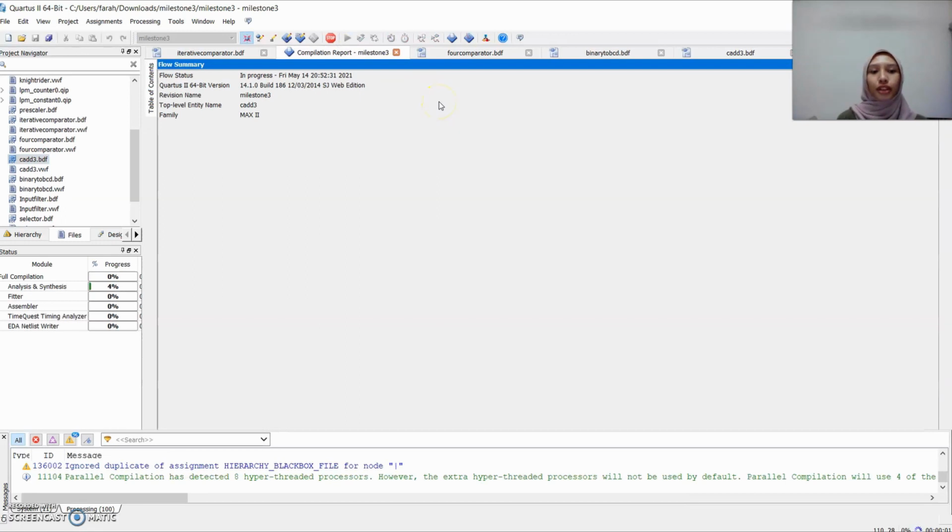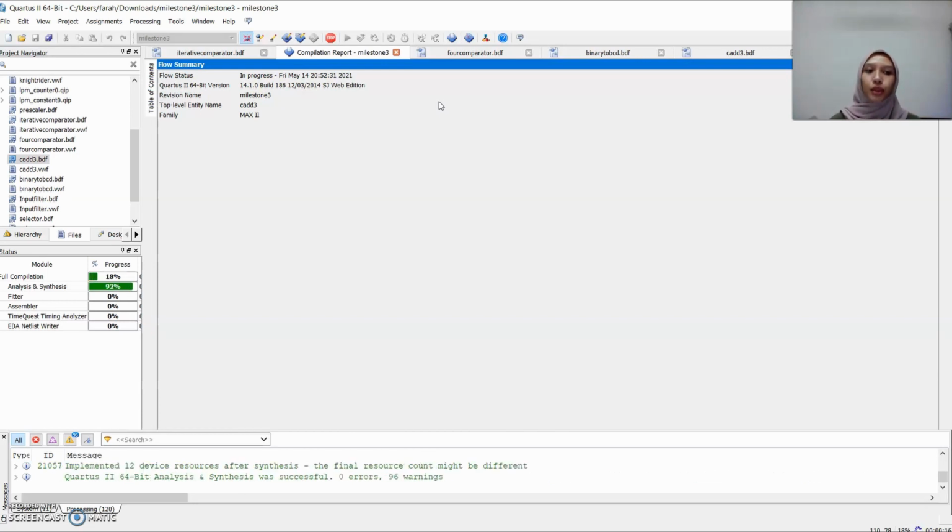For this module, the first 5 inputs will remain unchanged at the output, and for the next 5, the adder will add 3, and after that the input will be don't care or invalid for BCD.